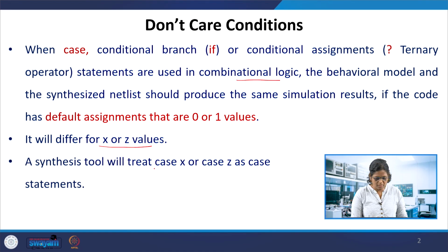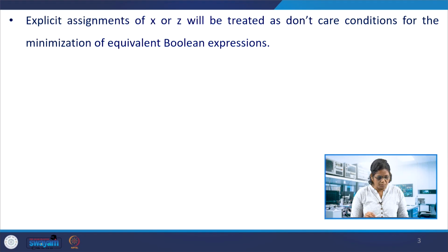The casex and casez, which are written in the case statements, are treated as case statements only. If you have explicitly assigned x and z, these are treated as don't care conditions for the minimization of equivalent Boolean expressions. So, to minimize the Boolean expression, the logic of the circuit, x and z are considered to be don't care conditions if you specify them in the Verilog code as x or z.